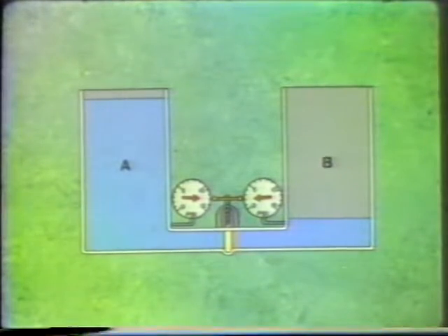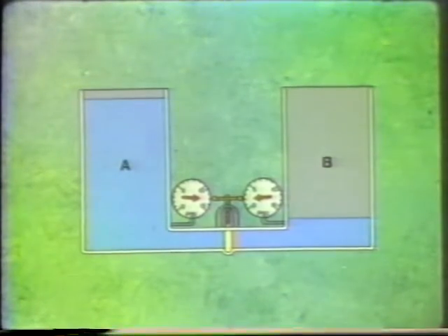That is about an 11 psi difference in pressure between the two tanks. This means that there should be flow between the two tanks because there is a pressure differential. But because the valve in the line is closed, there is no flow.